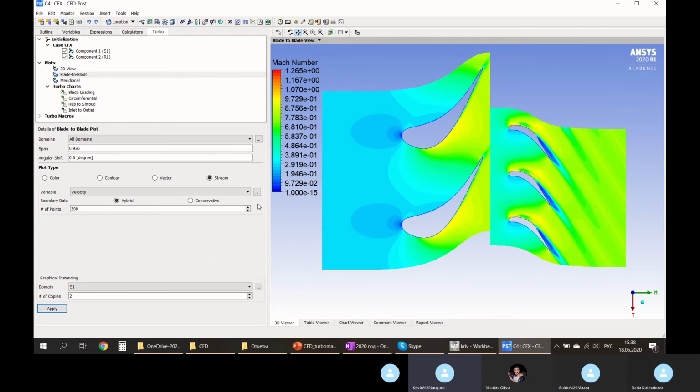How do we understand and know if the model is wrong? Because we don't need to make modifications to the blade and everything. Do we keep this model until the end, or will we have to change it if some results are not good at all? Of course, first you need to follow some basic principles, like increasing or decreasing pressure, temperature and velocity. Usually mistakes in changing these parameters mean not a problem in, for example, the blade profile, but usually problems in your model.